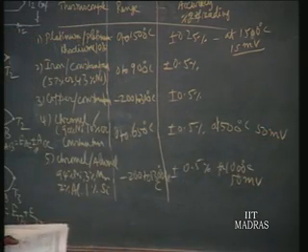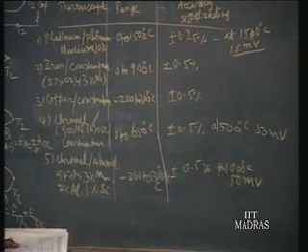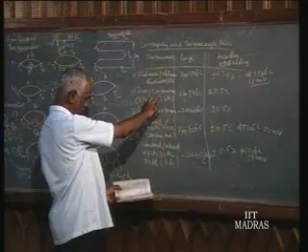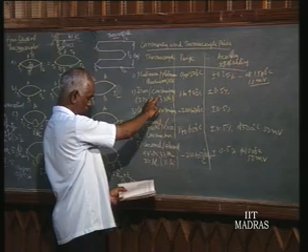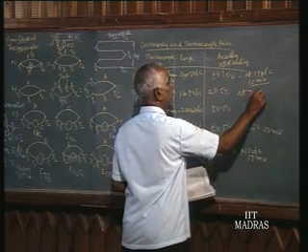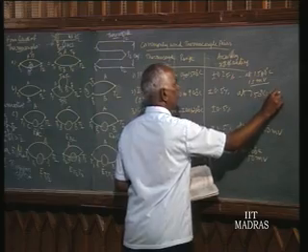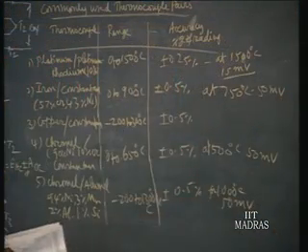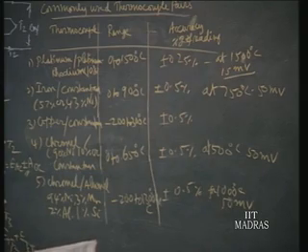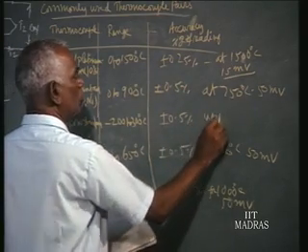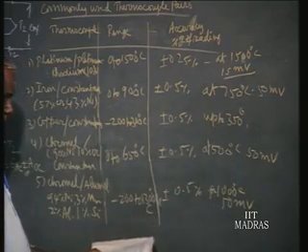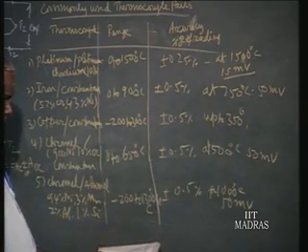Iron constantan develops 50 millivolts at 750 degrees centigrade. So from these characteristics, copper constantan has a measurement range of up to 350 degrees alone, and it develops at that temperature around 15 millivolts.